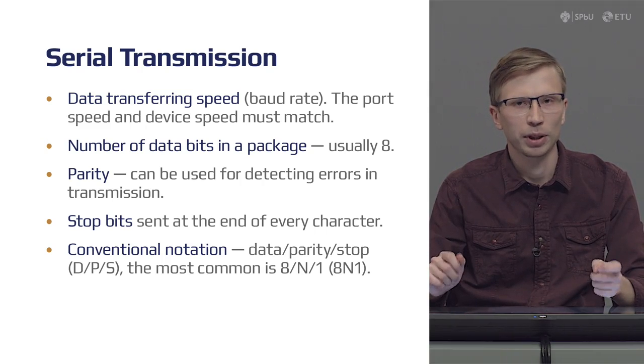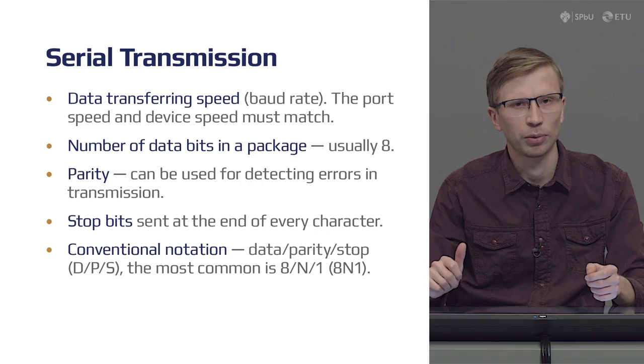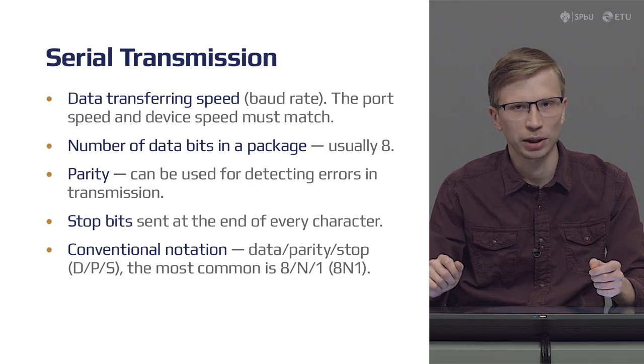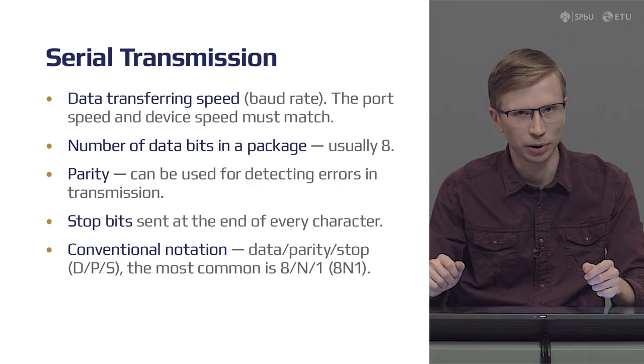The data-parity-stop conventional notation specifies the framing of a serial connection. The most common usage on microcontrollers is 8N1. This specifies 8 data bits, no parity, and only one stop bit. We will use this notation for all our future work with Arduino boards.